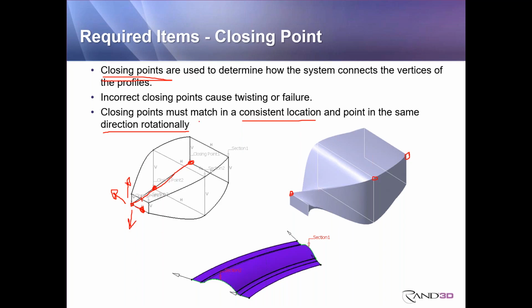And you're really thinking about a rotational direction. If my arrow was pointing, let's say, down or to the right, I am basically going around this rectangle counterclockwise. If my arrow was to point up or point to the left, I'm then basically going around that circle or rectangle clockwise. And I need to be consistent. So again, when I'm over here on this last section, I need to make sure that this arrow points in a direction that's going to match. Otherwise, again, you'd get twisted around.